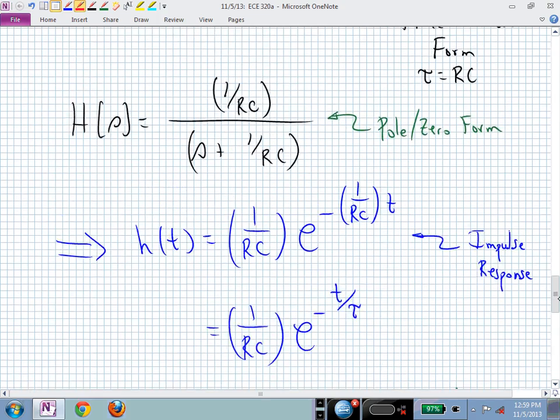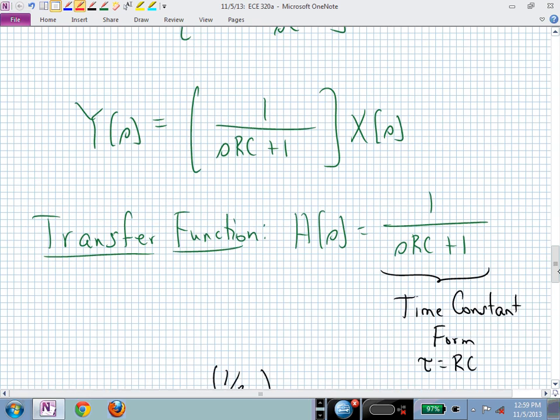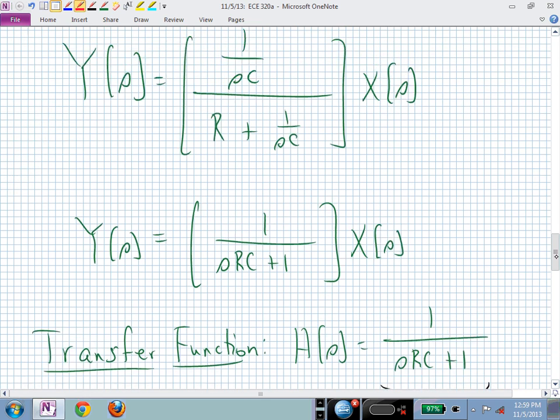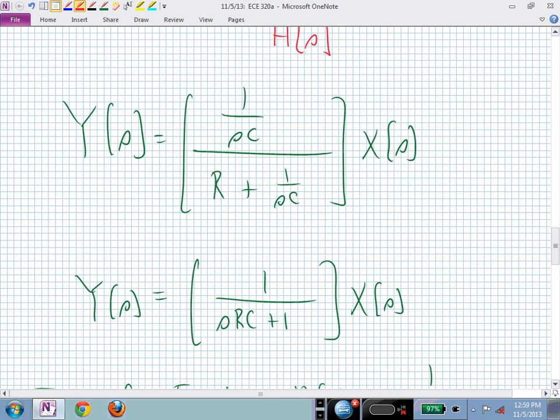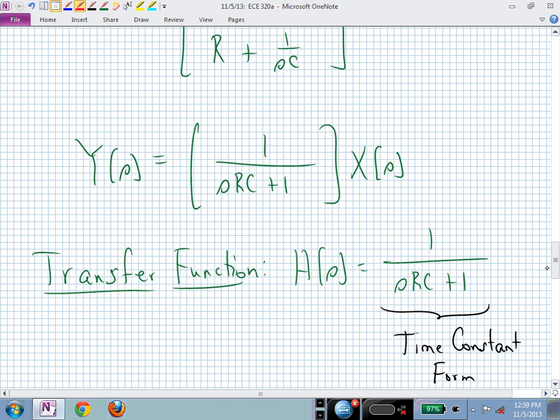All right, let's go back. We were trying to get to convolution somewhere, somehow. We now have a transfer function, H of s. What if I applied an impulse to my system? Which means I just excite it with something that's really big instantly, and then it's off. And that energizes all of my energy storage devices, which in this case is a capacitor, and then they start to decay their energy in that system or in that circuit.